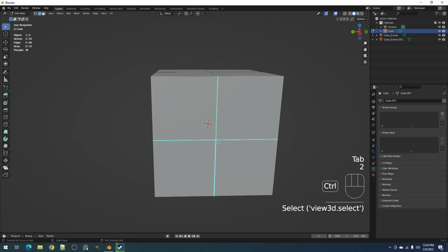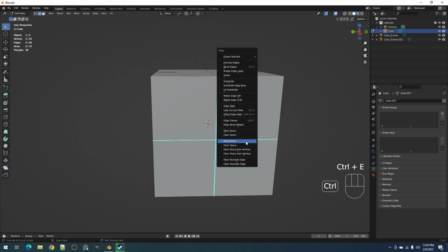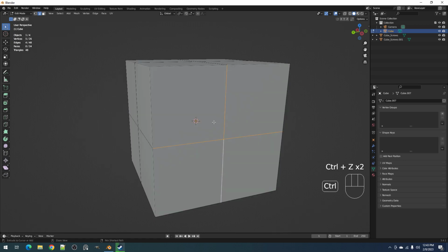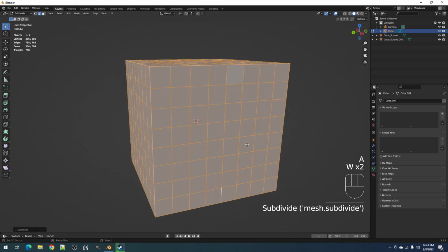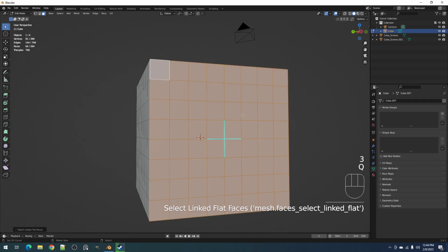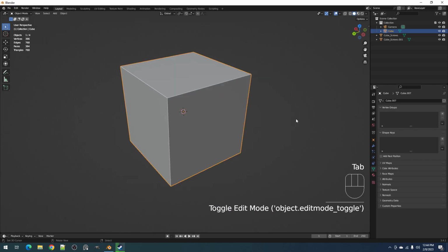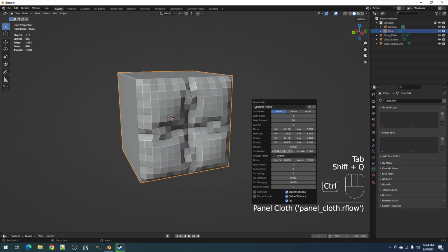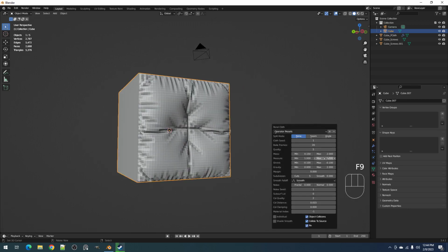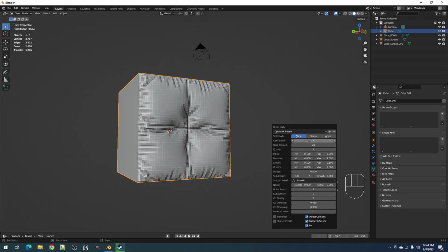So to create pinning on the center, you have to do a bit of geometry trick. You have to actually add more topology. Then we can use this mark sharp. There's no other way. I've looked up any other way to avoid the vertex group issue. There's no other way. So that we can use for pinning.